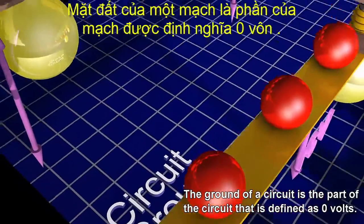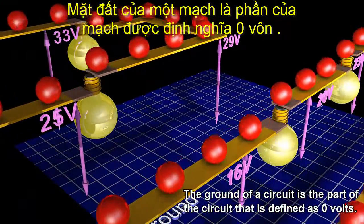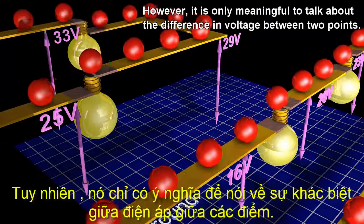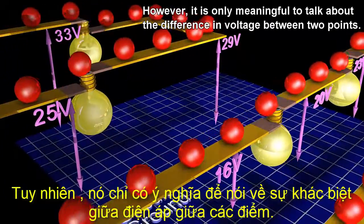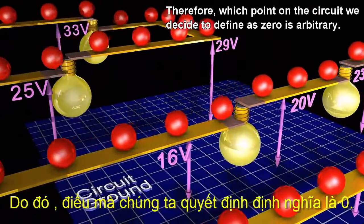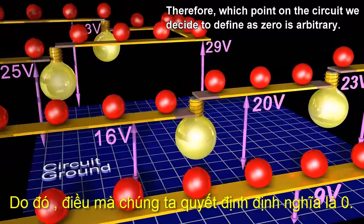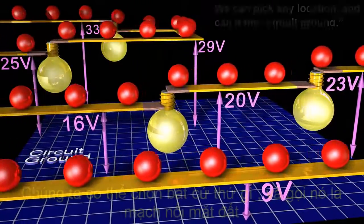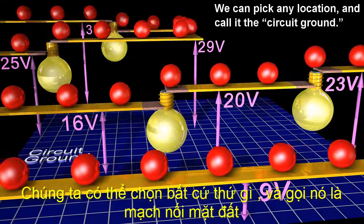The ground of a circuit is the part of the circuit that is defined as 0 volts. However, it is only meaningful to talk about the difference in voltage between 2 points. Therefore, which point on the circuit we decide to define as 0 is arbitrary. We can pick any location and call it the circuit ground.